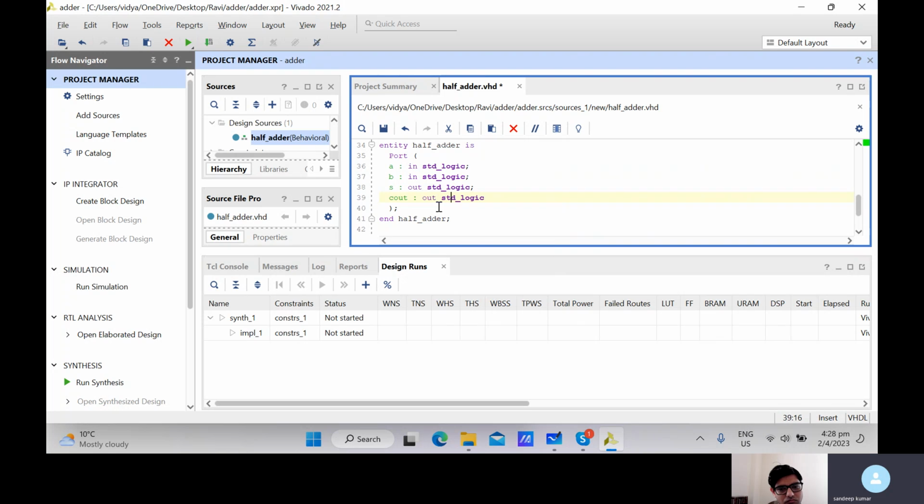Bus is bidirectional means, like I said about tri-state yesterday, the bus can be in a high impedance state. When we design an inout, when we are driving from outside, from inside we keep the bus in the high impedance state, and when we are driving from inside, from outside it has to be kept in the high impedance state. We'll talk later about this, as part of digital design, and how we use tri-state buses.